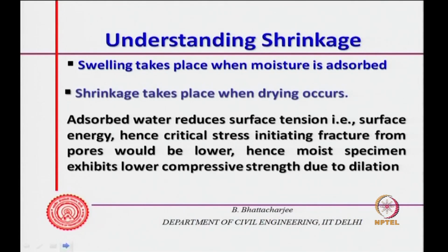So, adsorbed water reduces surface tension, surface energy, hence the critical stress initiating fracture from the pores will also be lower.